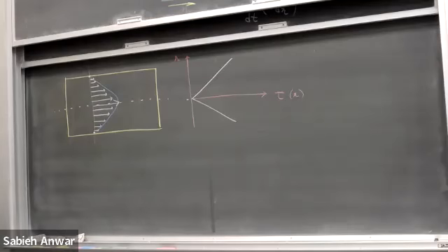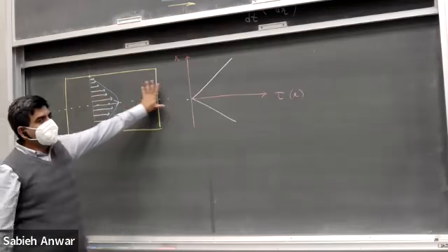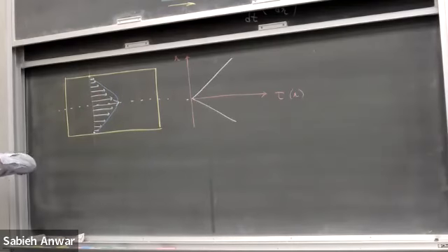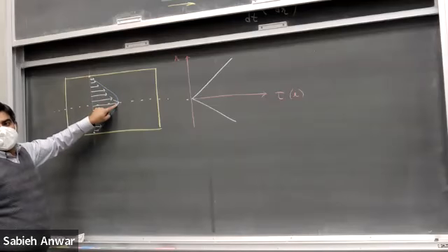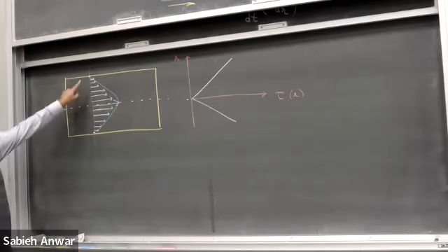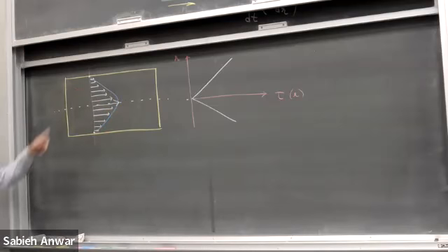But this flow has to develop. It does not develop instantaneously. It has to develop over time. So this is what happens in the steady state. And once it does that, it does not accelerate. This velocity profile just moves forward. But this flow has to develop. The development of this flow requires some acceleration, by the way. So once in steady state, the shear stress is maximum here, 0 here, and the wavefront develops. Now, what is the shape of this wavefront?